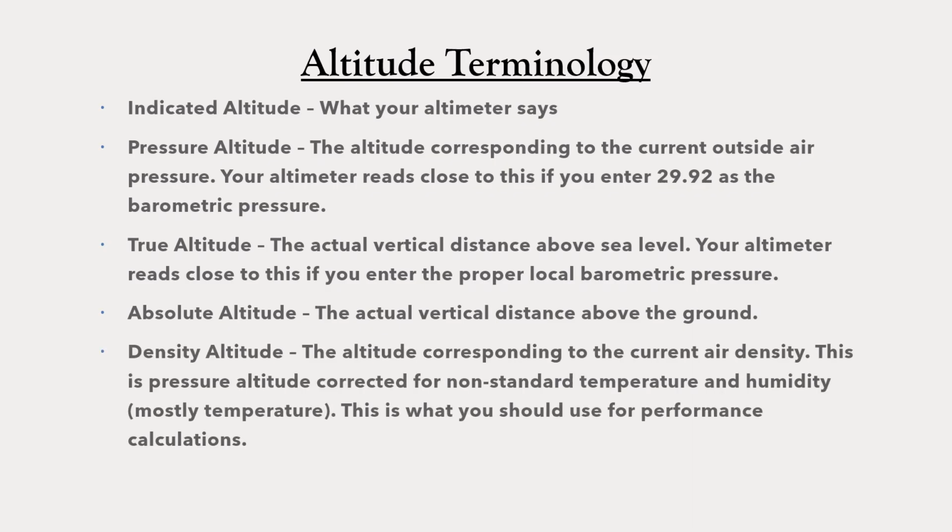And then density altitude corresponds to the current air density, which is different than the air pressure. This is the pressure altitude which is corrected for any non-standard temperature and humidity. This is what you should use for performance calculations.